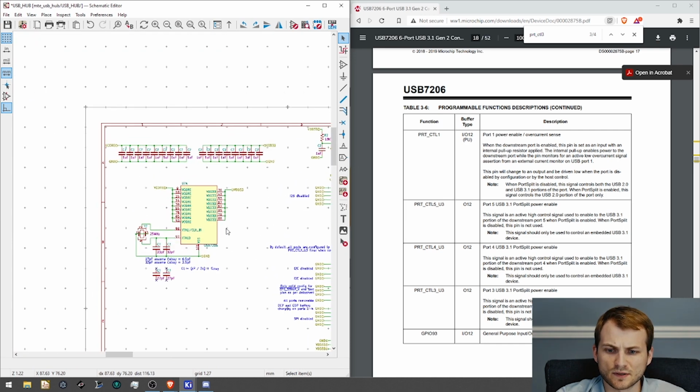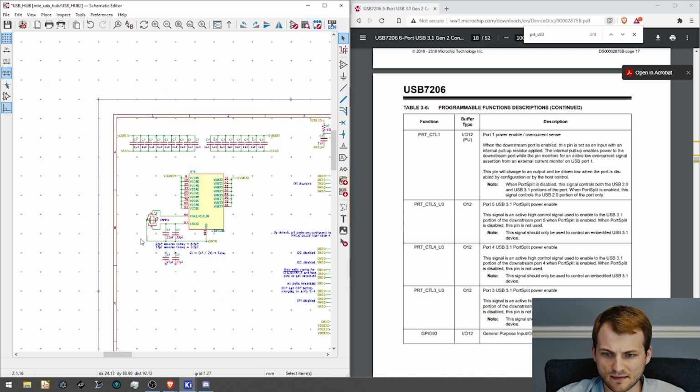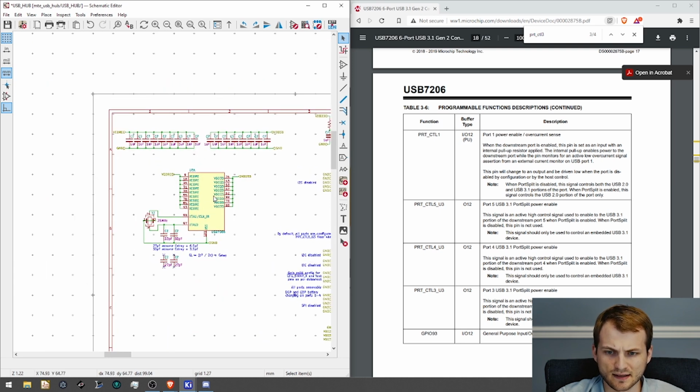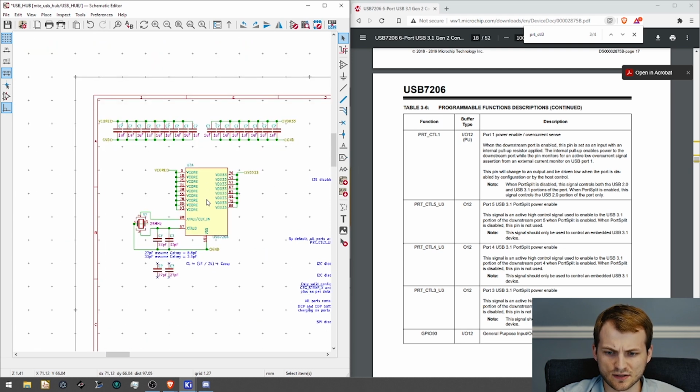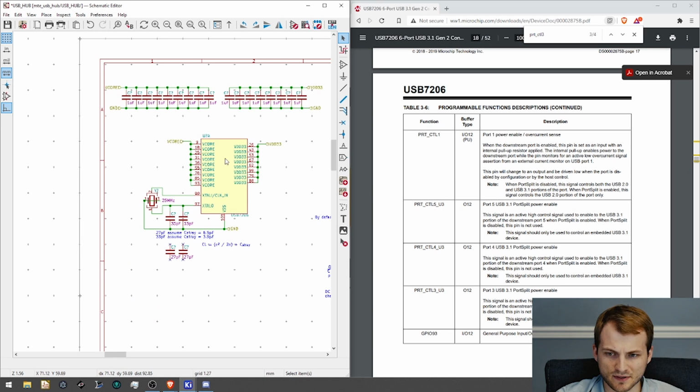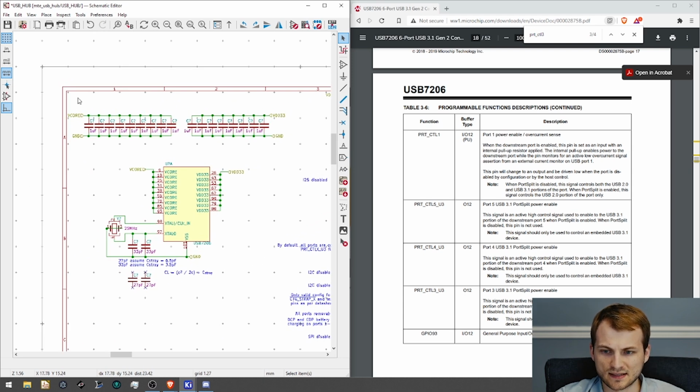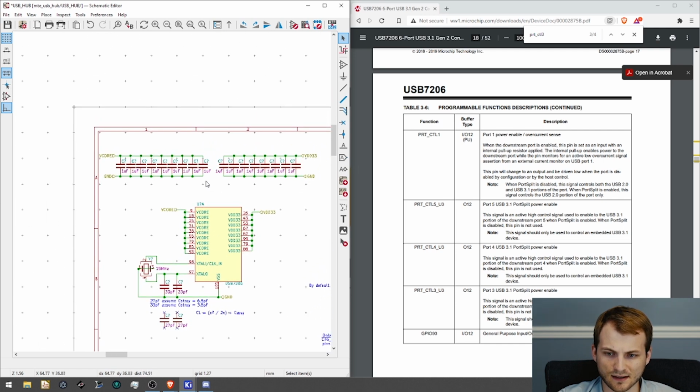So the last thing with the USB hub side is the power portion, and this, like I did in the second video, has 2 units. So this is just for the power side. And for the decoupling, there are 2 different power rails, the 3v3 and then the V core. The V core is either 1.5 or 1.2 volts nominal, I forget, but that will be tied in from the outside of the hierarchical sheet. Both of them need to be thoroughly decoupled.